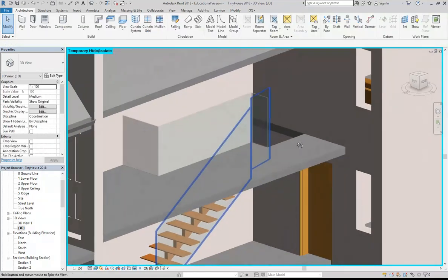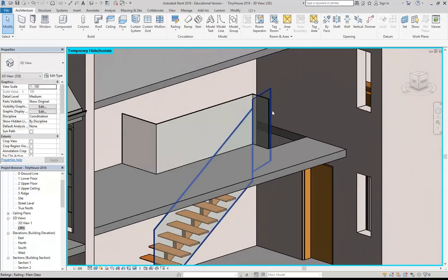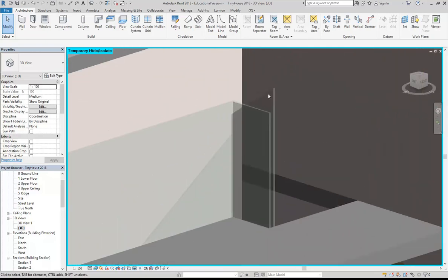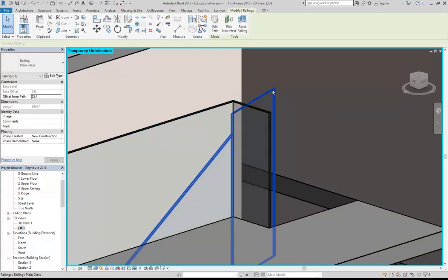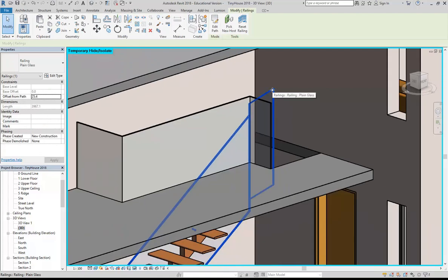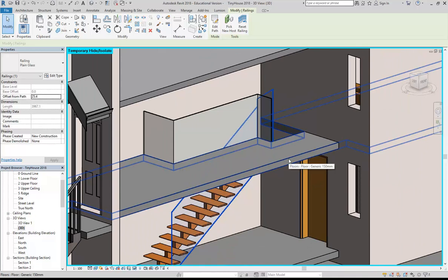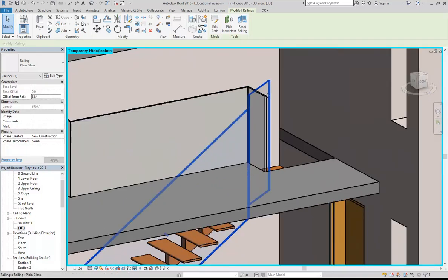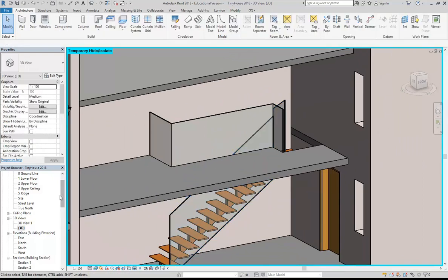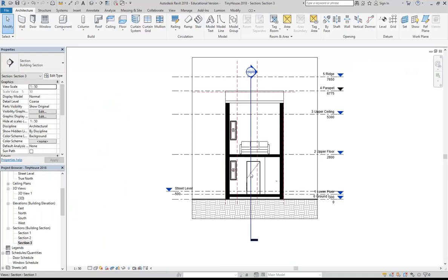And then you'll again see there are issues when you make railings that need to connect to other railings from a stair to a floor edge. You're going to get these issues with the way it projects. And that's why you'll often see that they make special railings just for stairs. And so here it's actually height correction that I need to put in. So I'll go back into the section just to finish off and show you that.